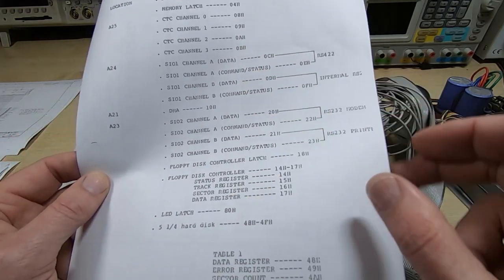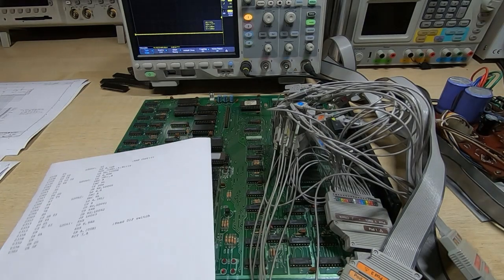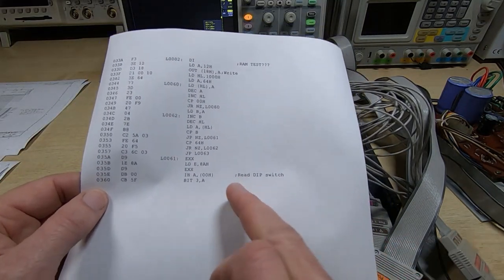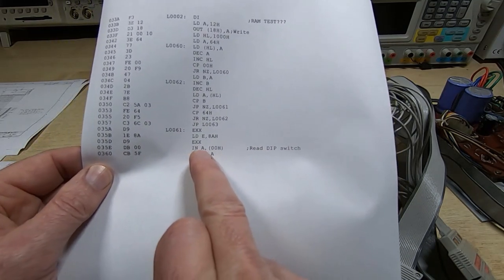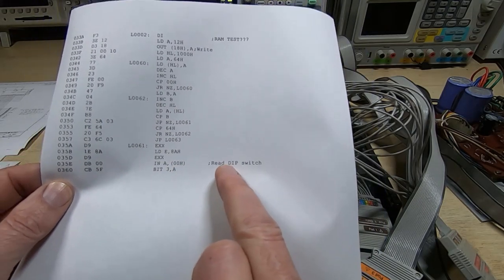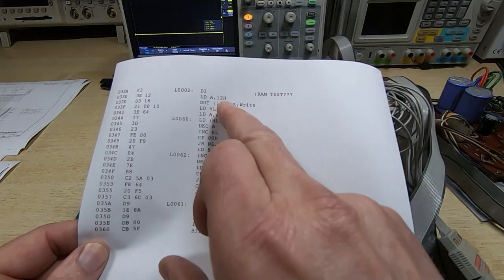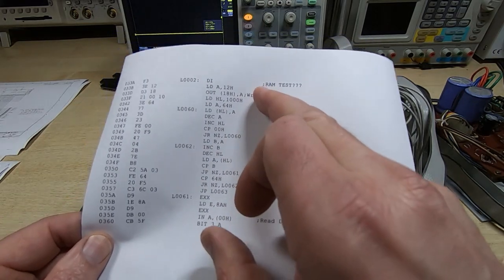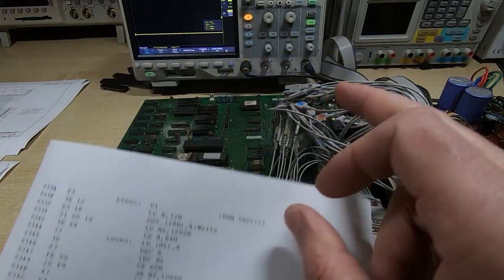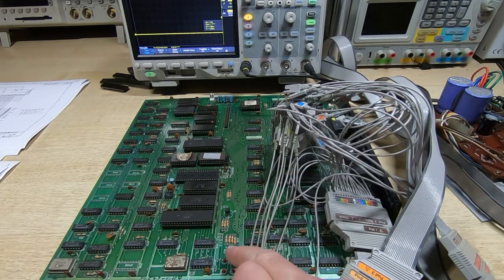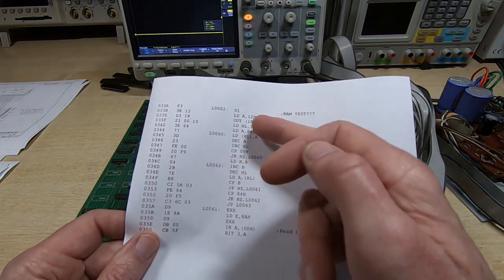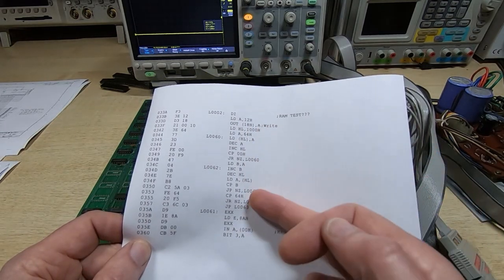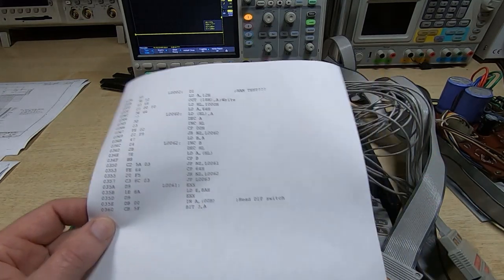So knowing this, what I can do is go through the code and start to comment it before we even run it. So for example, our port 0 is the dip switch, so I know that an in instruction of that port is reading the dip switch. So I did the same thing and I figured out that this bit of code is probably the start of the RAM test, which is the first test it runs and the one that appears to be failing because the first LED is flashing. So what we'll do now is fire up the logic analyzer, try and find this bit of code and try and figure out what's going on.